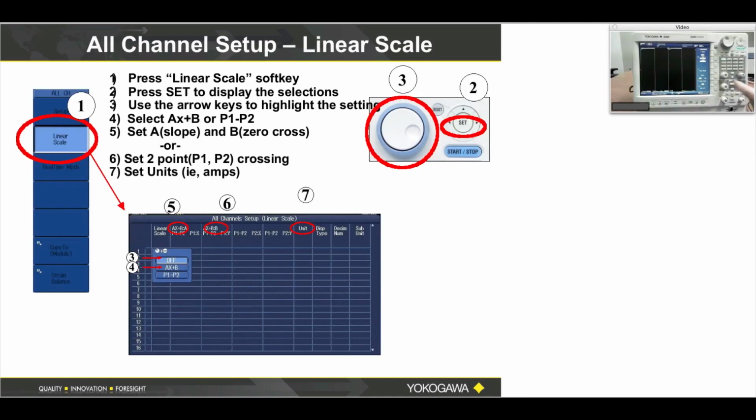Let's do cursor measurements. So if you have DL850 full video, go ahead and press the cursor button, which is at the tip of my finger here. Press type off soft menu button number 1 at my fingertip here. And press horizontal cursors. And then go ahead and get acquainted with those.